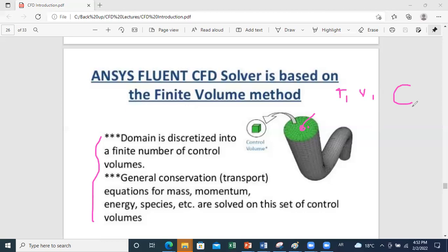You can use several methods to calculate the concentration of these species. We'll develop methods together. We'll see that you have what we call the Eulerian method, which consists of writing a concentration equation and solving for it. You also have the Lagrangian approach, which will track several particles within the space and try to convert trajectory information of the particles into concentration. So we'll go over these and learn how to compute the temperature, velocity, and concentration profiles within a space.